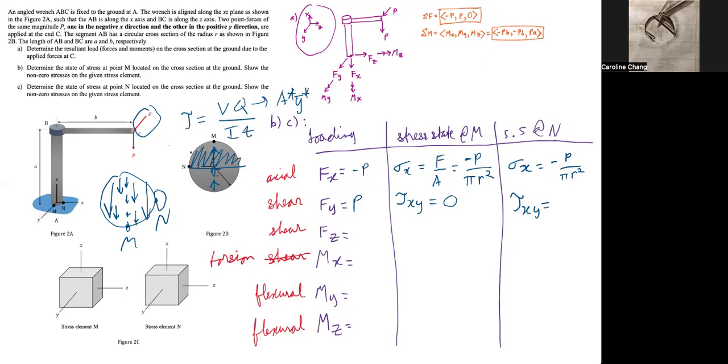We are at maximum area here, where the area is the area above the stress element location we're considering. And the Y bar star is the distance from the centroid of the semicircular cross-section to the centroid of the whole circle.